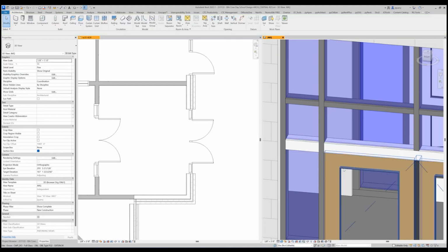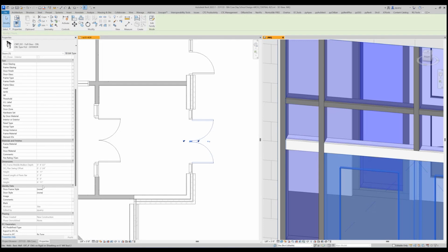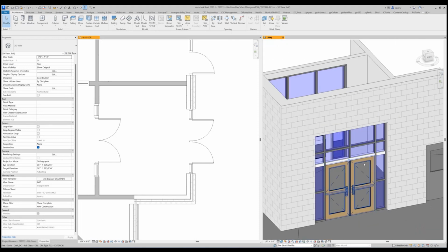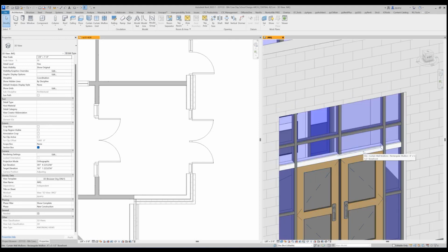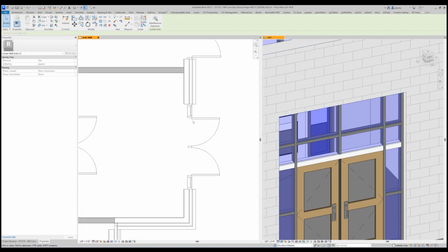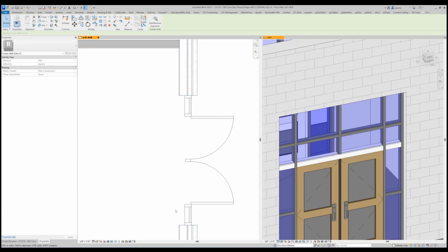So now this door panel's wrong. 6 foot by 6 and 11. So I have to adjust. Have you ever looked at a door schedule and you notice that it's 3 foot wide by 7 and 30 seconds? Or it's 7 foot tall, but it's 3 foot 1 and 27/64. That's because these vertical curtain grids are not aligned properly. That's how you get the shape horizontally, is you adjust these. That's why knowing that math is so important.